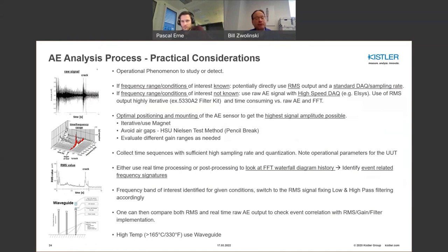So you need to really investigate that and look at what magnitudes of AE signals, where you're mounting the sensor, and what frequencies these AE events are at, so you can better create detection criteria to support your condition monitoring solution. So again, that's very important.